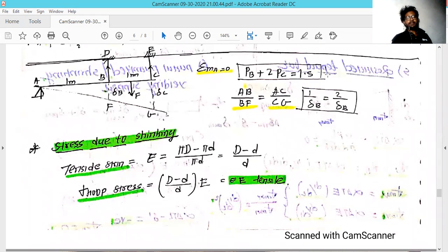So now this is another example, in which they tie a horizontal rod with two rods, or many other rods, and a different rod is used to pull those two rods, and the other end of this rod is placed at a hinge point. In that condition, if a hinge point is there, it is not able to move in the up and down direction. It is allowed to turn about that point, so moment about that point is possible.